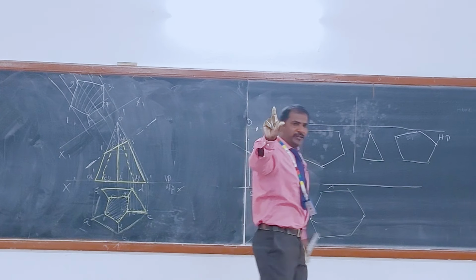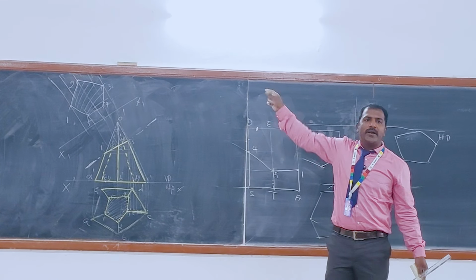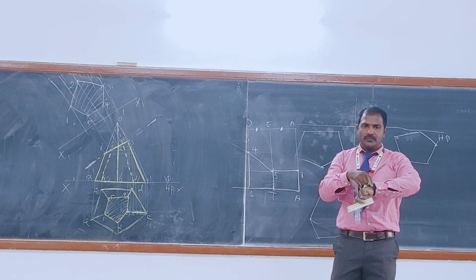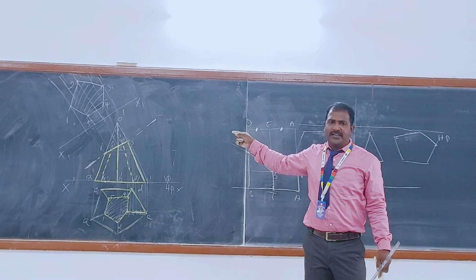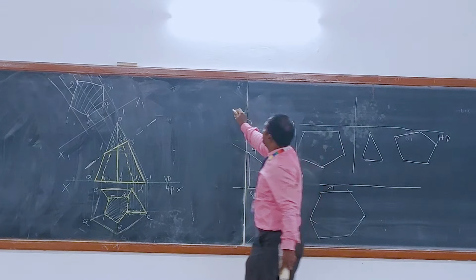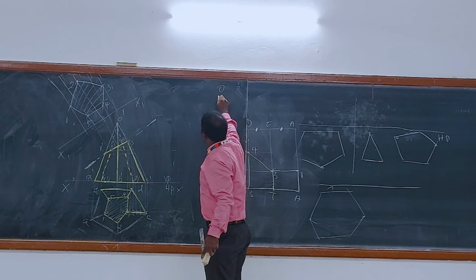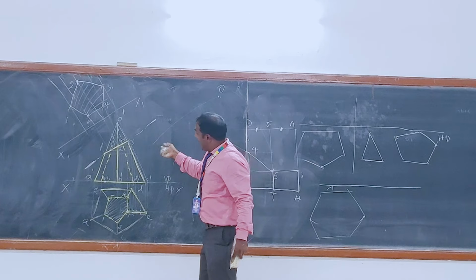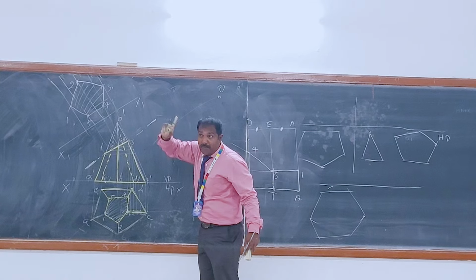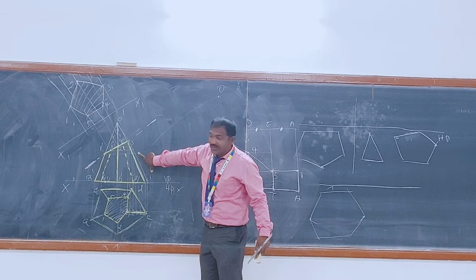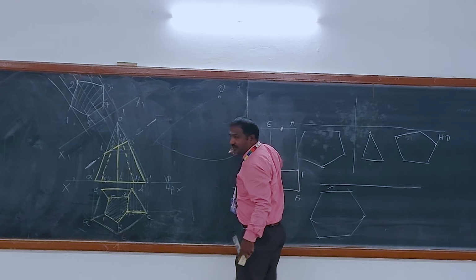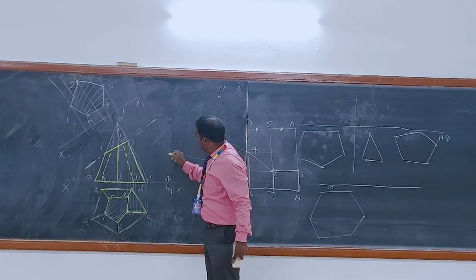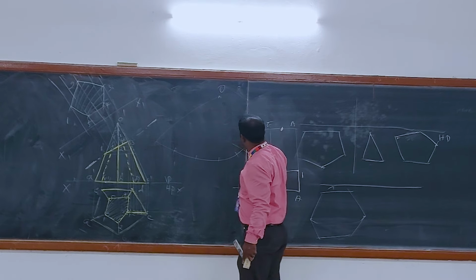What you are seeing is a prism. Measure from xy, mark from x1 to y1. Got it? You know how to develop this, I told you already. So mark the point O. Draw one line at any distance. Take the true slant distance, remember that, from O to this distance. Draw the arc, a big one. 35 mm, 30 mm, 30 mm, 1, 2, 3, 4, 5.